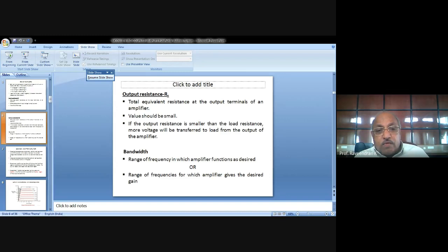So that is why, when you apply a signal with a high frequency, that high frequency signal will easily pass through the capacitor CE. Capacitor CE bypasses RE, transferring the signal to earth or the common point. From my point, the signal should not be wasted here. It should not drop any voltage here. It will make a short circuit path through CE to the ground. So that is the purpose of the emitter bypass, and that's why it is called the emitter bypass capacitor.